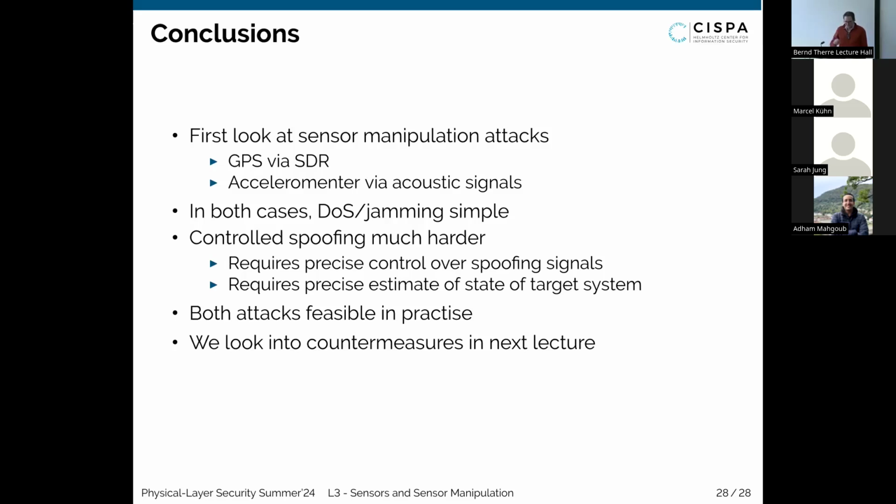Just that there might be other measures in target systems, not really countermeasures, that are built for normal reliability purposes, like, for example, the optical flow sensors or the extended Kalman filter variance monitoring, that could pose additional challenges for an attacker to take over and need to be taken into account when you do this kind of manipulation of GPS and sensors in general.